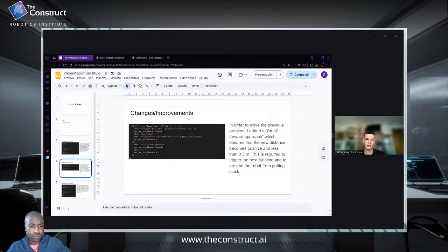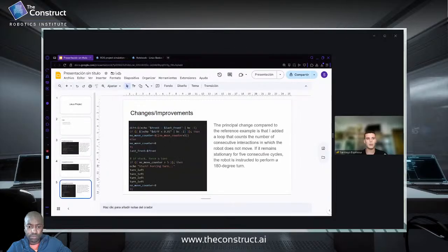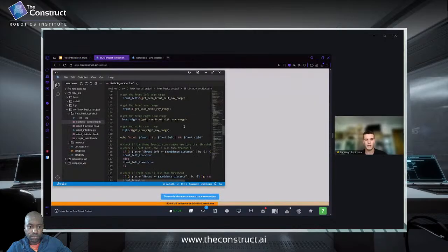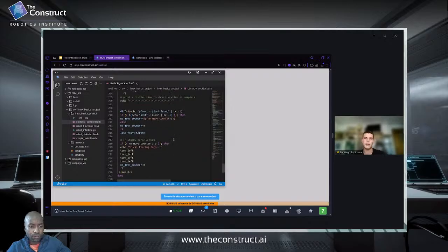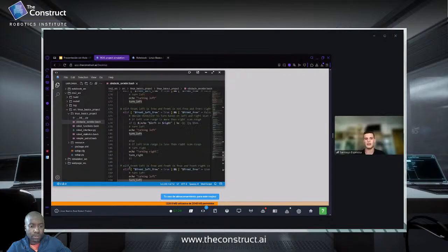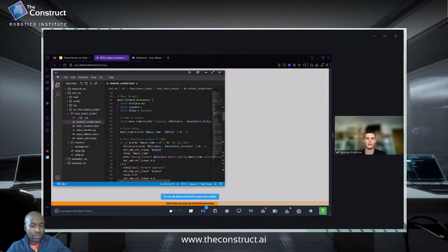Here I explain what I have just done, and another change I did is that at the end of the loop I put this. If during the loop the robot hasn't moved, and all the sensors have the same values, if it happens 5 times, I put a counter. I show through the screen that it is stuck, and I turn left 4 times, so it changes the direction 180 degrees. I did this before the solution of the problem, but then I realized it was the negative values.